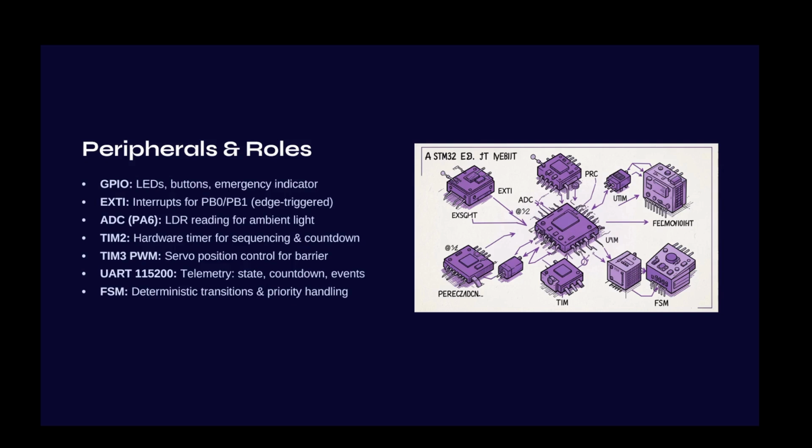Peripherals and roles. This project helped me learn several important STM32 peripherals during my internship. GPIO. GPIO stands for General Purpose Input Output. I learned how to configure GPIO pins to control traffic LEDs and read button inputs. It was my experience in directly controlling hardware using software.